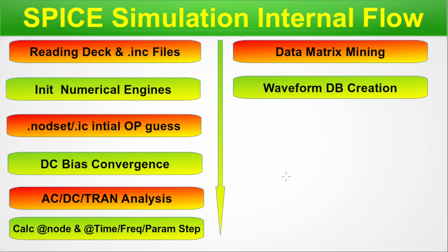In case of NGSPICE, we have a very easy option to plug in GNUplot and directly throw the output into the GNUplot GUI, where it shows the current and voltage characteristics with respect to time as graphical plots. Multiple windows are plotted as per the instruction. We have already shown this in the last episode. There are 3 circuits we have shown, and the different graphs we have shown are already there.